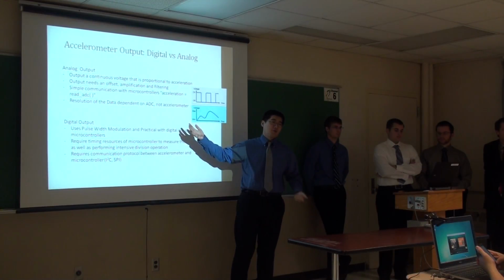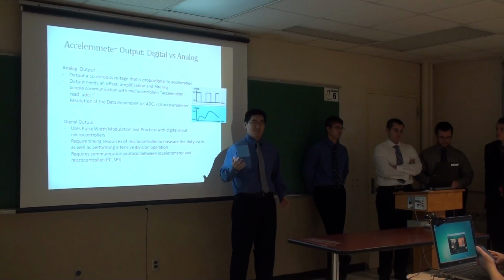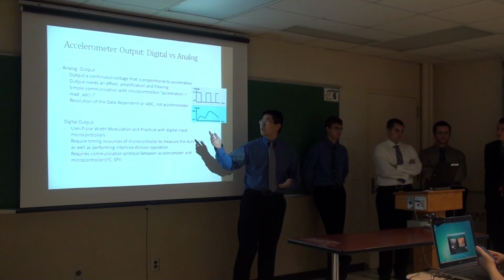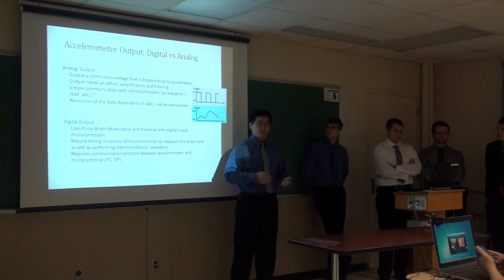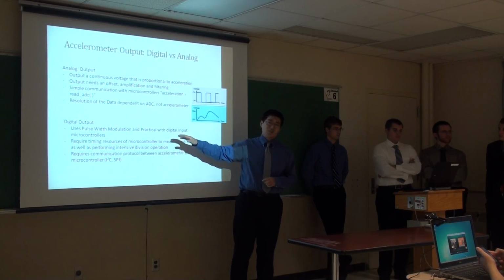The one we're using for our project, the MSP430, has the read ADC command, which literally takes the input and converts it to a digital value, which we can use for coding. So that's really good. And the resolution is completely dependent on the microcontroller and not the accelerometer.